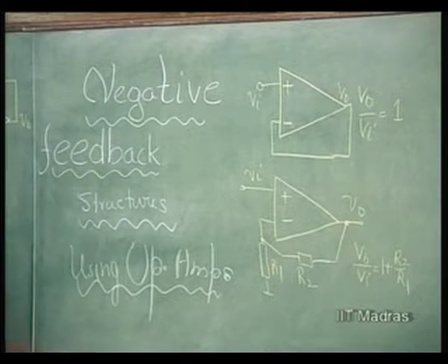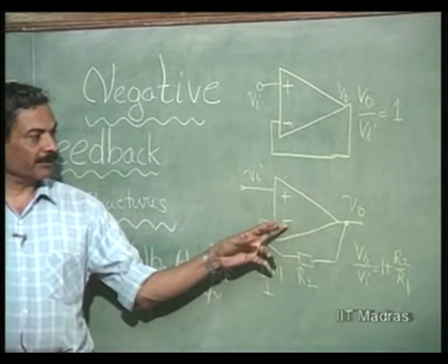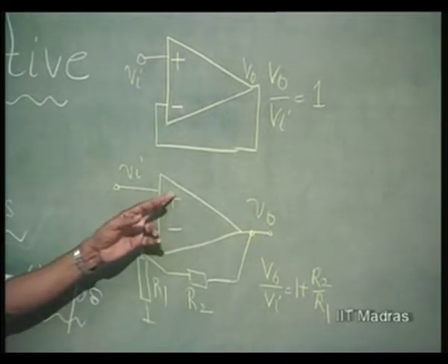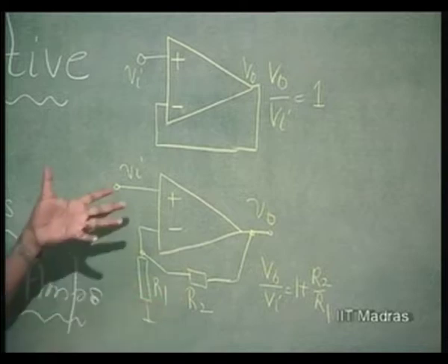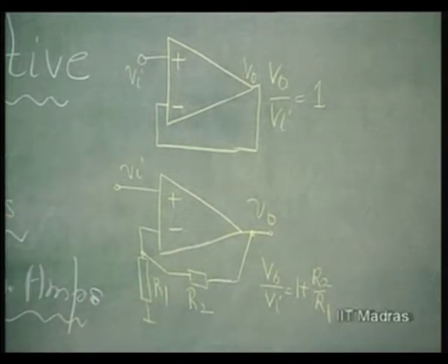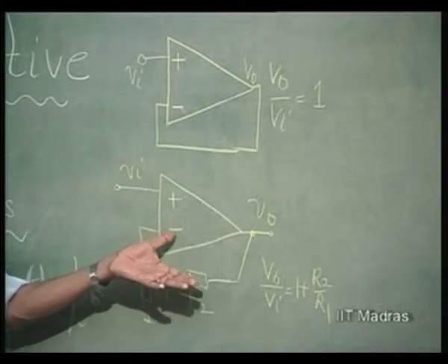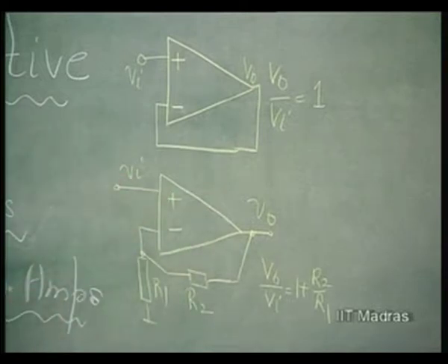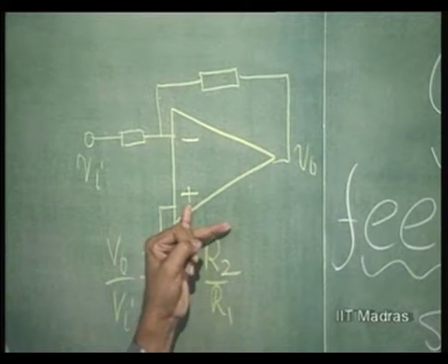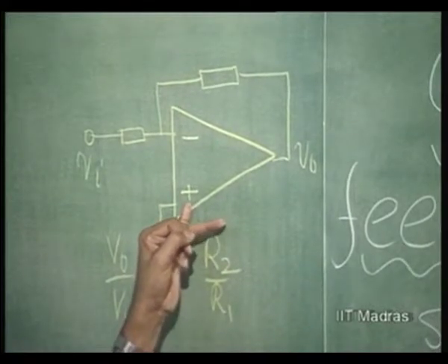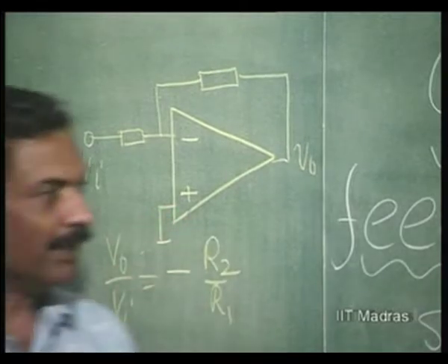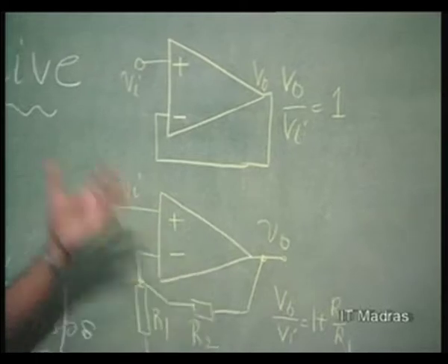We had digressed a little bit. We were discussing negative feedback configuration. In order to differentiate it from positive feedback, we went over to positive feedback configuration. For example, this is a negative feedback configuration. To show that structure looks similar with this minus, this plus, but that structure is entirely different. That is one with positive feedback, regenerative positive feedback, and with hysteresis, when this becomes plus and that becomes minus. Similarly, when this becomes plus and that becomes minus, that is another regenerative feedback configuration. So, this should be kept in mind, that the feedback changes, the characteristic becomes different. That is a nonlinear circuit.